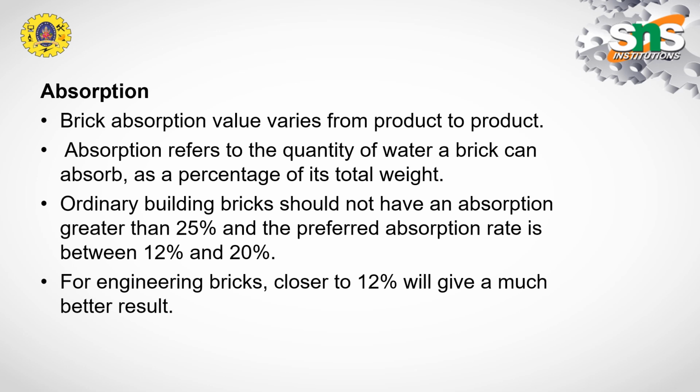Next comes the absorption. Another important property is the absorption of the brick. The value varies depending on the brick, but there is a standard value. An ordinary brick should not have an absorption greater than 25 percent of water when immersed.